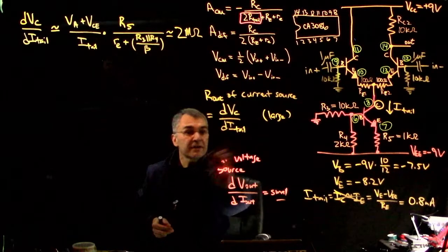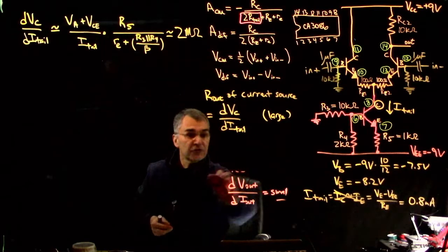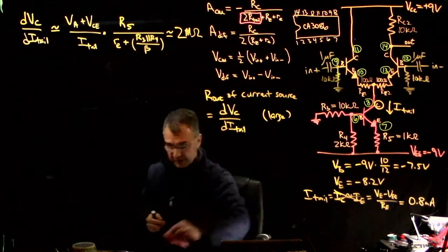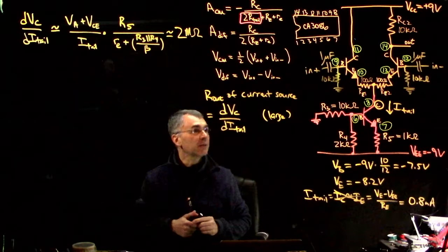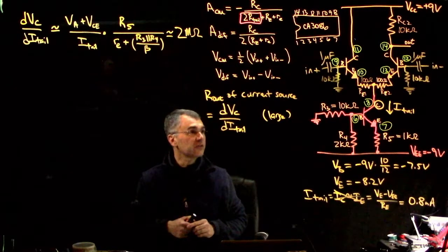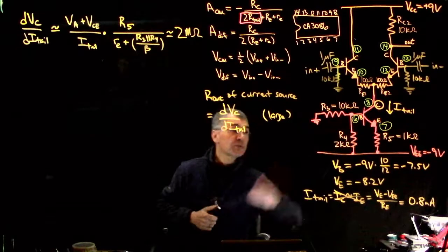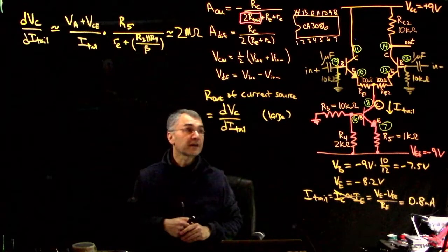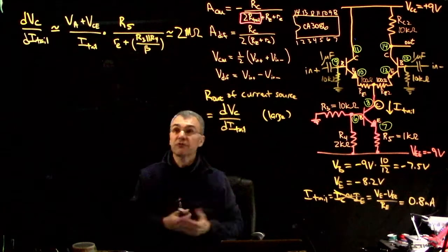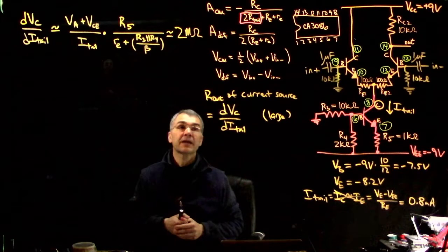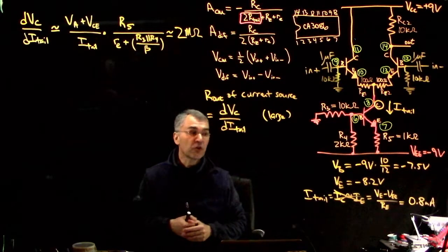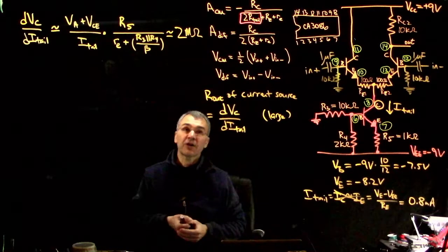And it turns out that when you make a current source with a bipolar junction transistor, for reasonable choices of parameters, you can get an output resistance for that current source on the order of mega ohms. We can measure that in circuit. In this course, the only way we know how to do that is actually to measure it in Circuit Lab.